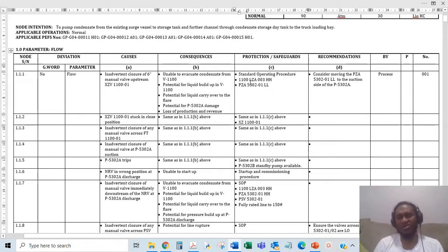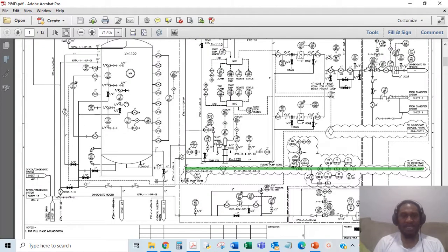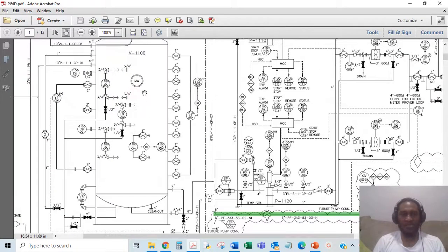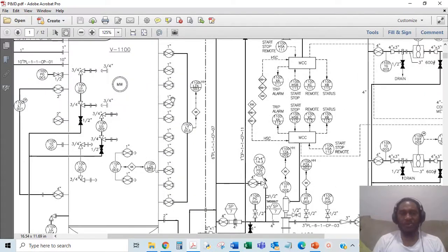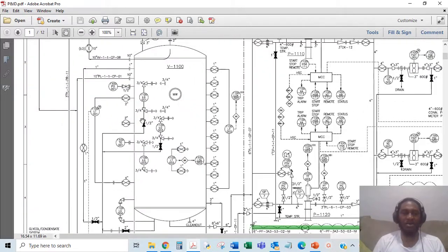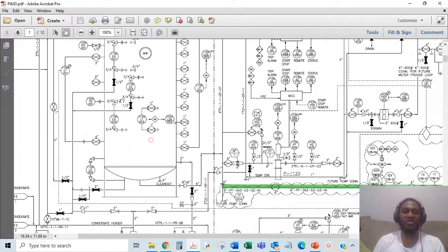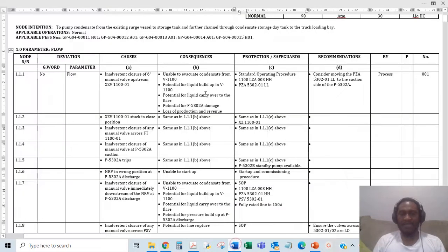the plants. Then we also have another safeguard, which is a trip, 1100 trip 003 high. Which means if you're not having any flow in this, there's a potential for a buildup in here, and there's a high trip, which is this. When this vessel sees a very high level of liquid, it would trip, and that trip would probably cause a close of some upstream shutdown valve, so that we don't keep on filling this and have liquid going to the flare, because that could be very dangerous. And so that's protection.